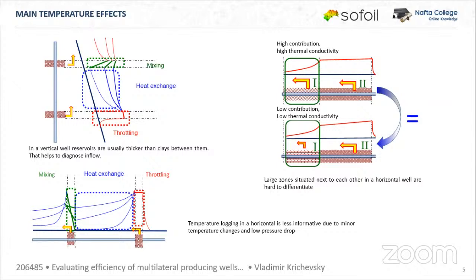But in many cases, we do not have fractures, like in this case, for example. We do not have any fracs, and we have a huge borehole. It's more than 2 kilometers long. And everything flows. And in this case, we might get a picture like on the right, where we have several layers right next to each other, and each layer is contributing. And this picture is not as contrasting as you might expect. And the methods of quantification of the inflow could fail you, unfortunately. I mean, the simple methods could just fail you.